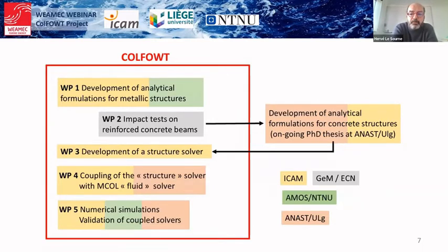5 work packages constitute the project. First, new superelements for spar-type floating offshore wind turbines are developed in work package 1. Work package 2 includes drop tests on reinforced concrete beams to validate the simulations.